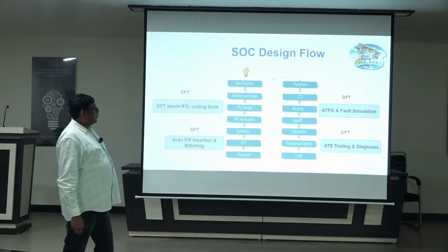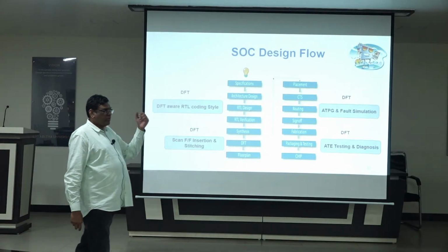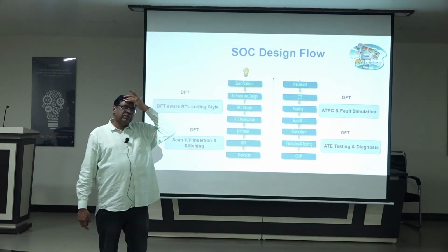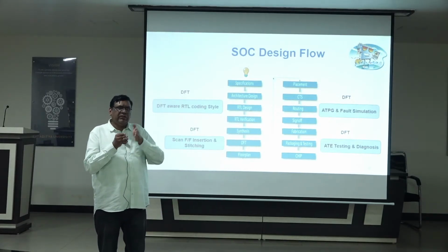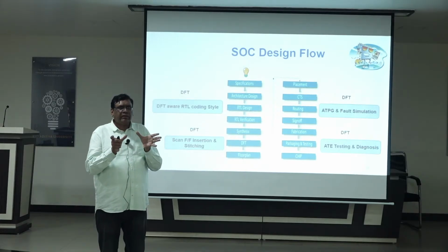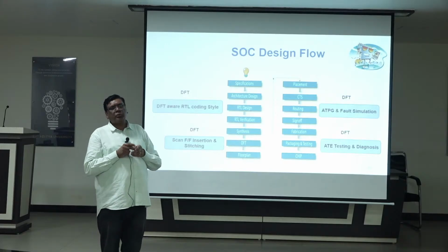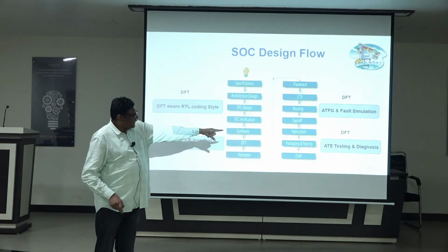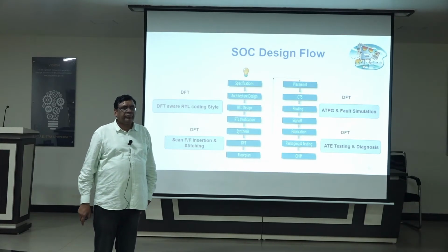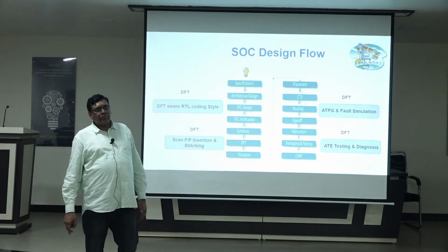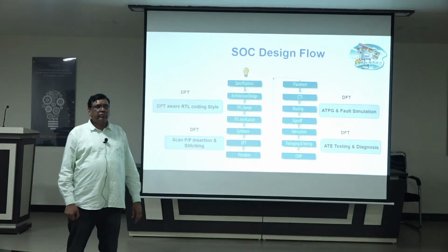Maybe you have heard about shmoo plots. What they do is, for different voltages and different frequencies, they make a plot of how the chip is working. That plot we call a shmoo. That generally happens at the ATE testing stage. If possible, I will show a shmoo plot whenever I do the demo.